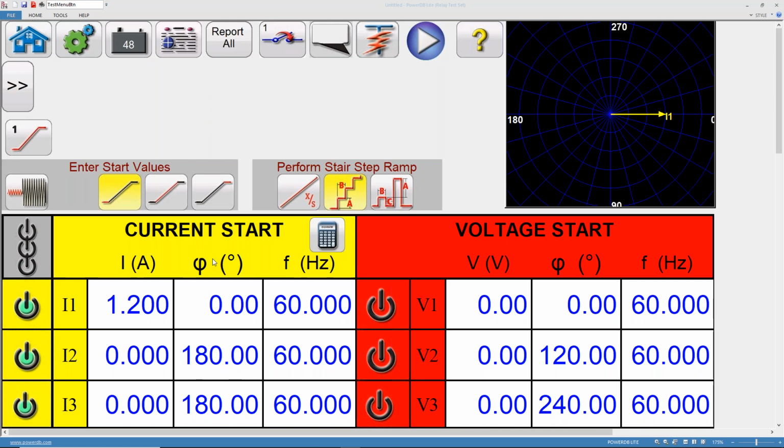the relay tap. And on the BDD nameplate itself it'll have the tap value, and then on that nameplate will also have the pickup value. And so that's what we're going to use. We're going to use that pickup value, which in this case is 0.30, and we're going to take it times the tap value and give us our values to run our pickups on. We're starting at some value below pickup, and then we're going to ramp into the pickup until the relay operates. So let me get my relay setting.